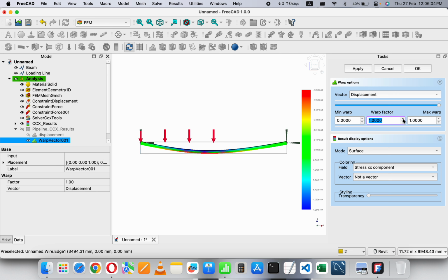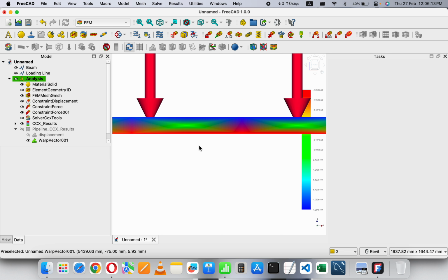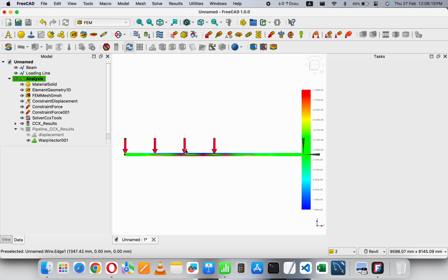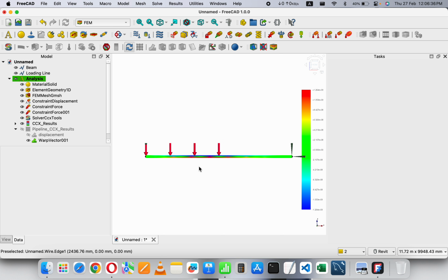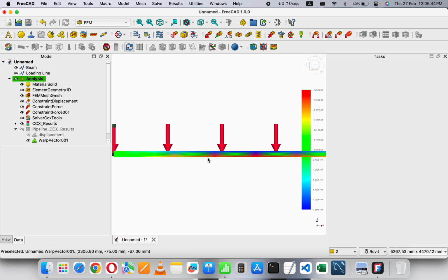If you want, you can do it like this. I will prefer just try it once. Click on OK. So this is the stress, which we will use to calculate the moment. This is the stress which is causing the moments in the beam. In static analysis, in theory of structures, we calculate moments. Why? To calculate the bending stress. This is the actual bending stress inside the beam.